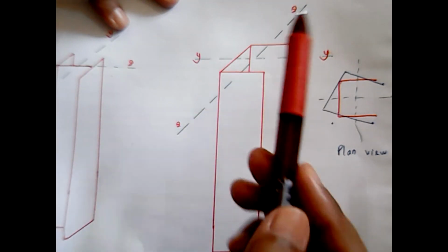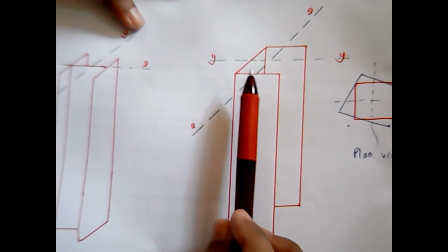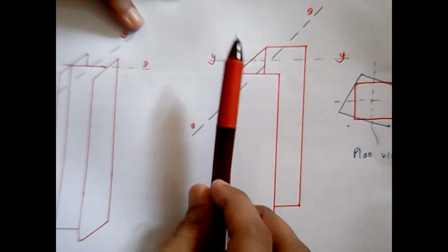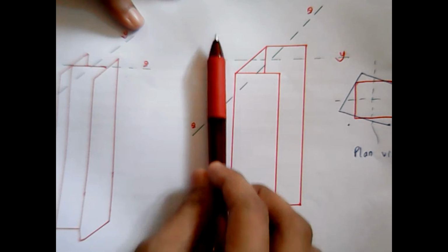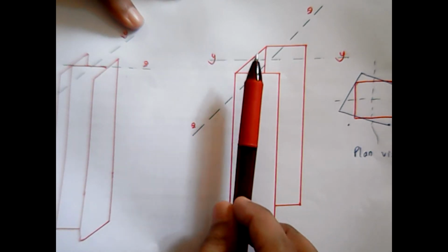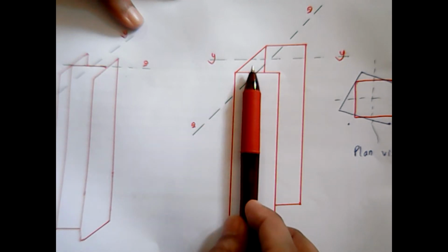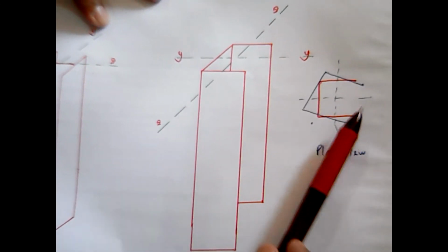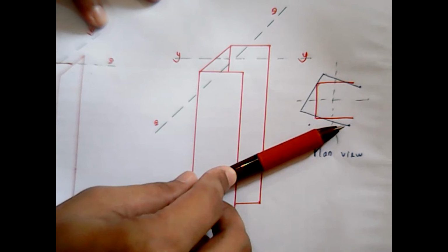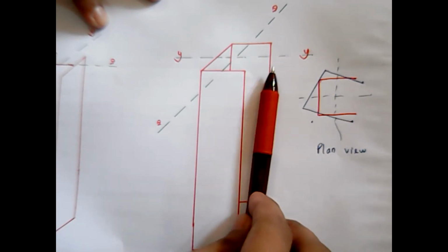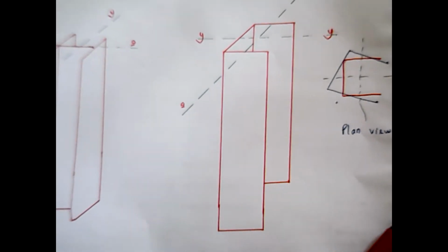So in this particular case, the cross-section itself may be subjected to torsional and torsional flexural buckling. So meaning that the structure can twist, and the whole member is also able to buckle.